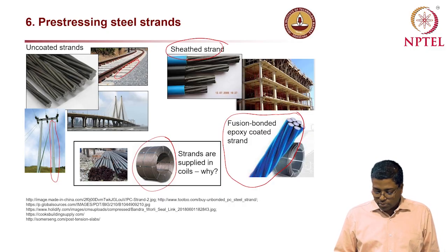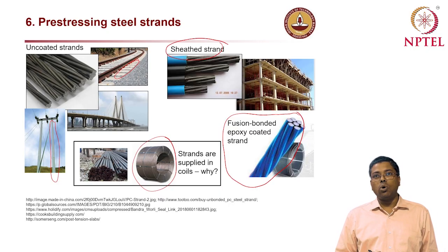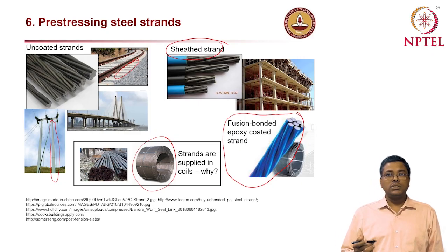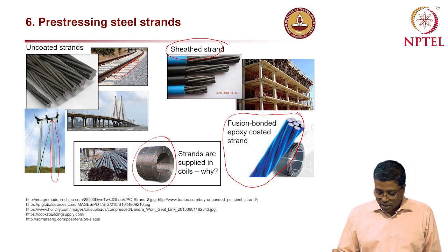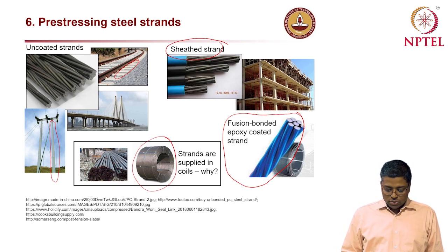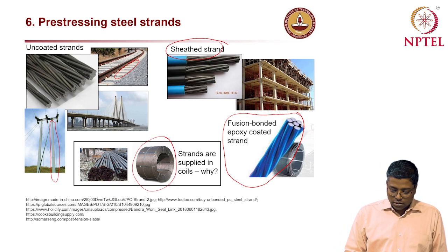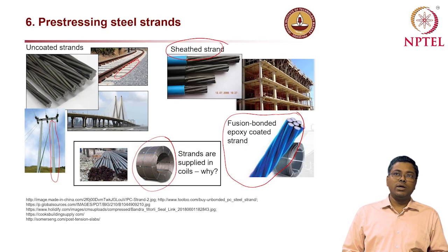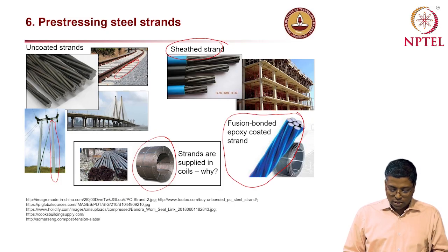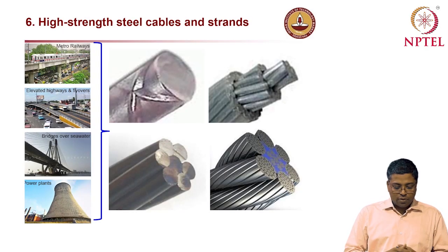Otherwise, the coating will degrade, and if there are scratches, it will not serve the purpose for which it is designed. So when you use coated rebars, we have to handle them very delicately, so that mechanical damage and UV induced degradation is avoided.